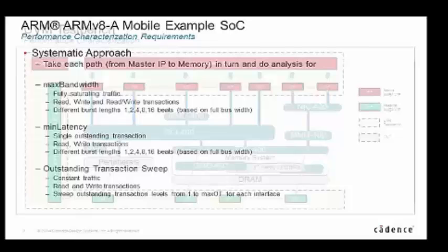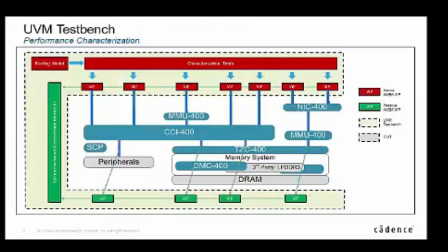And so that asks the question, what address patterns are you using and how do they affect the performance of the DDR controller? It's a very complex environment to actually understand the min, max and variability of latency. The other thing that jumps out on these diagrams was that the read bandwidth is actually quite a bit higher than the write bandwidth, and that's to do with a complex issuing limitation of some of the ARM IP. So you can only get about 5 gigabytes per second of write data, which is capped lower than the read data.